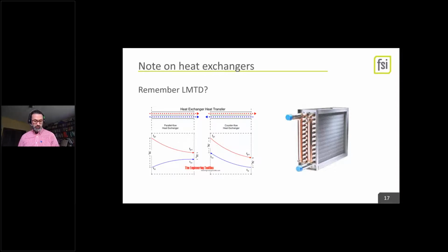What I can say for certain is that many very old systems, and we've worked in a lot of old schools with systems from the 40s and 50s, hydronic or steam systems, those coils are massively oversized. They're way more capacity than that school needs, and you can get that in part by, if you've got a more modern control system, you know how far open the control valve opened. If the control valve never opened past 60 or 70%, you've got way more coil than you need. So there's a way to kind of back your way into, do I think this will work?